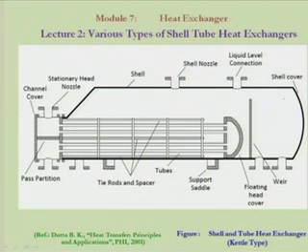that on the shell side portion, there will be a huge space, and this huge space is to accommodate the vapor that is coming during the boiling operation. Care is also taken to see that there is no entrainment of liquid bubbles. So, this kettle type heat exchanger is being used particularly for reboiler operations, where we need enough space for the vapor to be generated, and that vapor is gradually taken up. Okay.